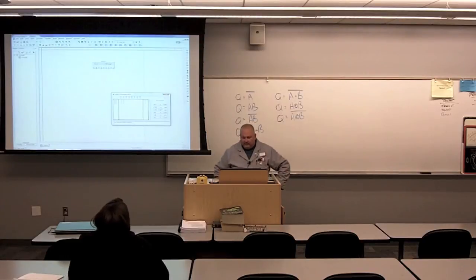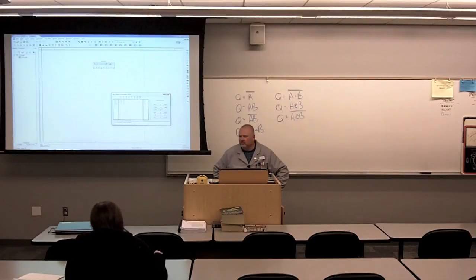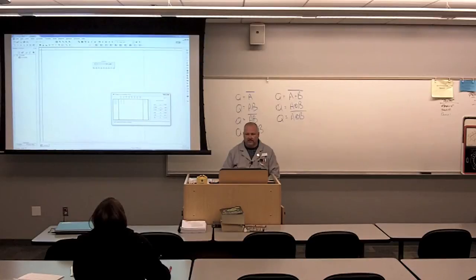Okay. So let's read through this again just to make sure. This is, again, 34.1c, okay? Let's go with a read back here. A and B not, or A not and B and D, or B not and C not and D, or B not and C not, or A not, B, C and D. You concur? Okay, now comes the fun part.